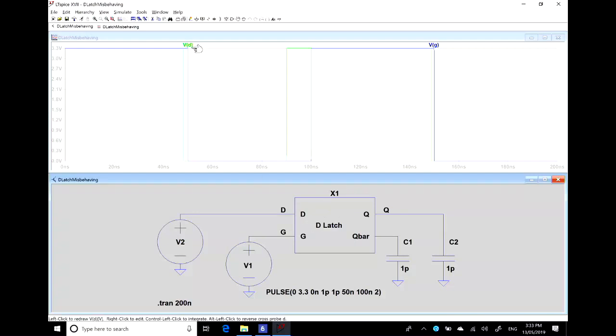And then suddenly we slam the gate shut, which means that this input change is no longer present on the capacitors there, and they just get stuck at the last value they were at. And so in this way, by making this gap precisely the right distance, I can get the input capacitors stuck at 2.5 volts. And then the rest of the circuit, where there's the feedback loop, can maintain the 2.5 volts for a short period of time because it's an equilibrium point. That's the theory. Let's see what happens in practice.